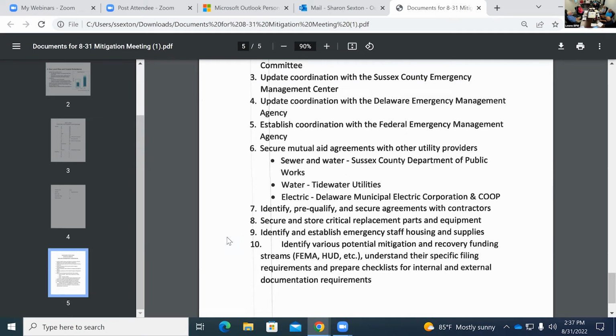This is the grain-oriented silicon steel that's used in laminates. It increases the performance of the transformer by about 7%, depending upon design. They wanted to relax that so they could go back to the old style steels, but that would mean putting in assets for the long term that are 7% less efficient. The EPA and I think the Department of Energy came back and nixed it.